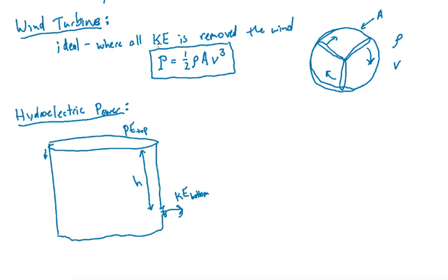So basically what happens is you'll have the energy that's stored that you're going to get out of this, and again, this is assuming 100% efficiency, that you take all of the kinetic energy out of this water at the bottom. But again, just like up here before, it's not possible. We can only get a fraction of it. All of that energy you start with is mgh, however high the water is above this.